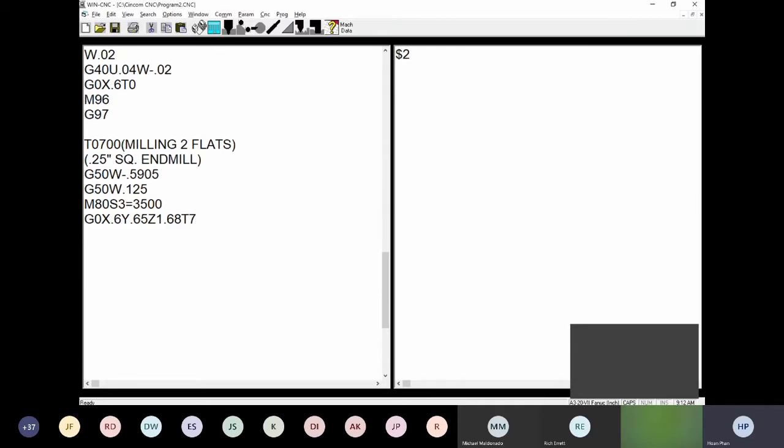and make the flat as good. So right here, you all know that we're going to be using the live tooling, so you will know that we use the G98. But before that, we're going to go down to the right diameter of the flat. It's going to be X.315. And then we're going to start milling from here, G1, G98, and then Y becomes minus 0.65. And then the feed rate you can put in here, and it's going to be inch per minute.